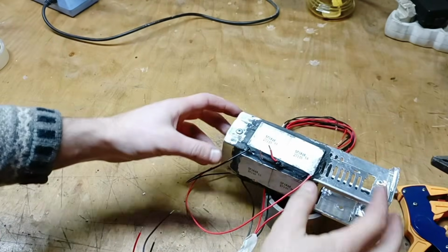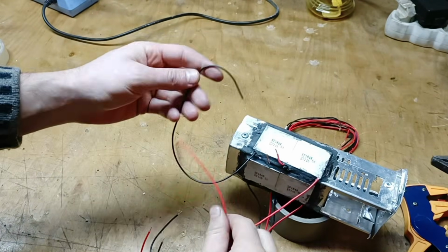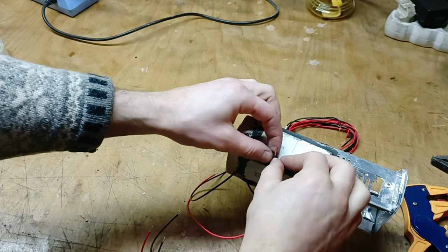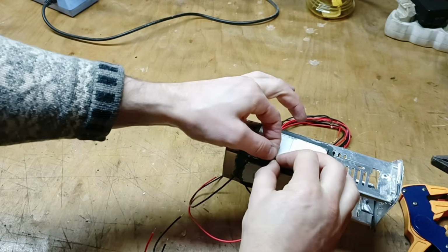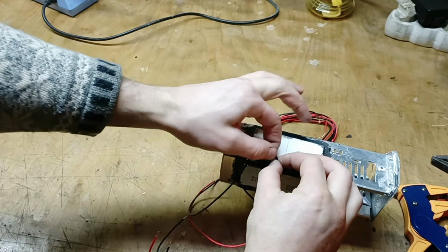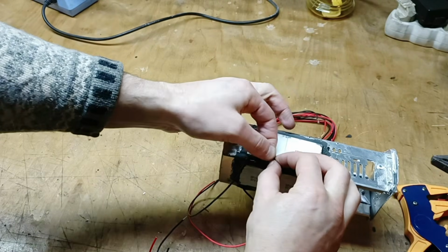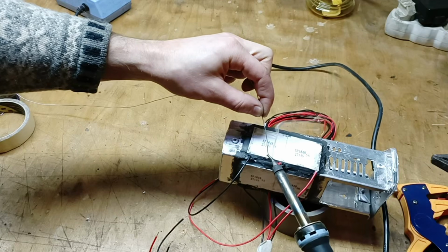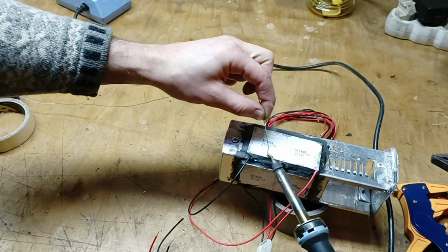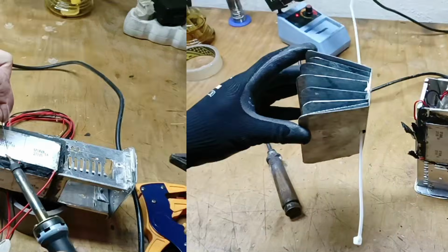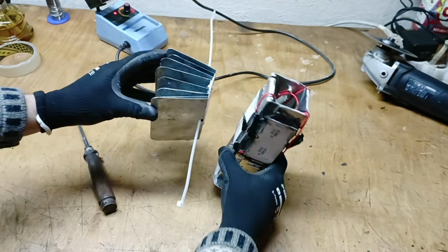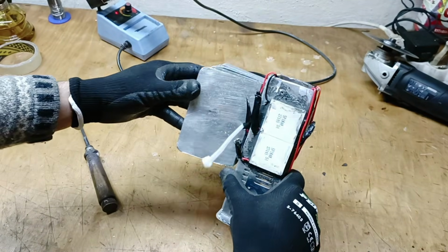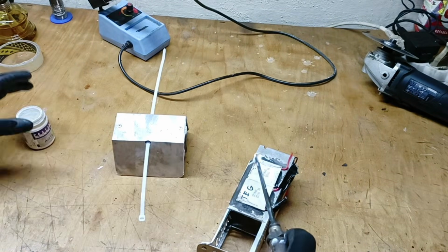And now it's time to make some electrical connections. I will connect all the Peltier cells in series. This means that the positive of one cell connects to the negative of the next, and so on. This will allow me to achieve a higher voltage across the entire cell pack than that of even a single cell. After making the aforementioned connections, I can begin attaching the heatsinks to the cells located on all sides of the